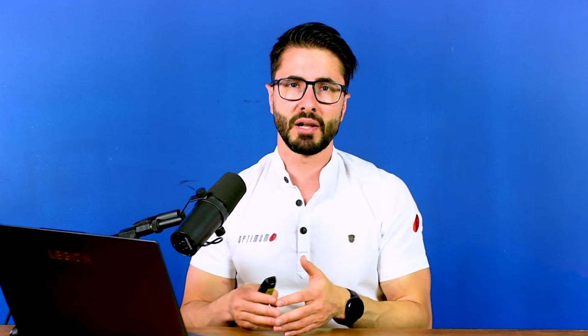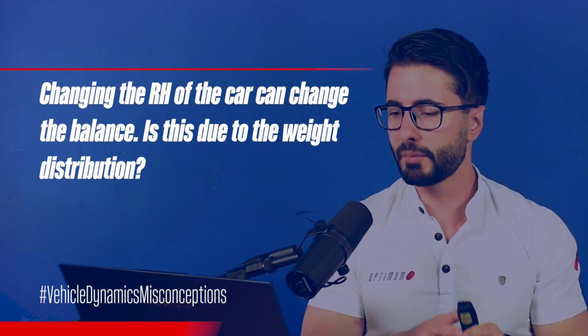So whenever I make damper changes, I'm looking at the damper speed histogram to quantify two main metrics: damping levels, which is a comparison between low and high speed movement, and also damping bias, which is a comparison of how much time I spend in bump versus rebound. It helps you to analyze not only damper changes, but it helps you understand if the damper changes you are making are significant enough. It helps you to compare different cars, for example. And a last point is that it helps you identify issues with the dampers. So whenever you see your damper speed histogram KPIs shifting, it is a clear indication of a damper or damper sensor issue.